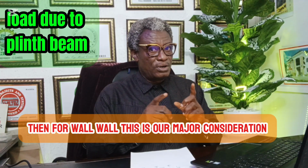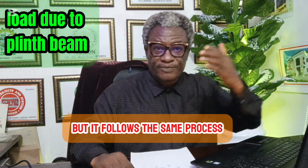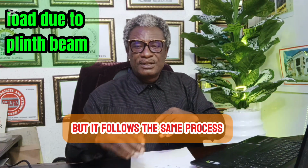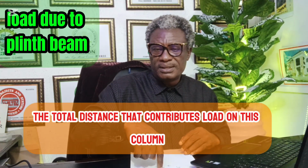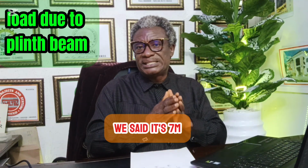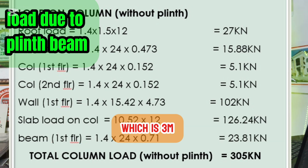this is our major consideration now. Let me take time to explain that, but it follows the same process. The total distance that contributes load on this column, we said is 7 meters. So we multiply that 7 meters by the height of the wall, which is 3 meters.